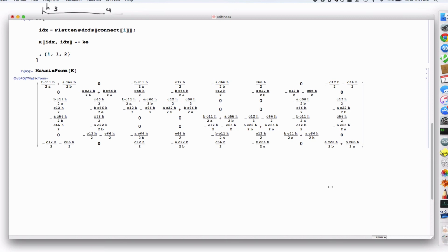I like Cubit because you can script it, right? You can drive it with their own internal commands, or you can drive it with Python. So you can script it and make everything parametric. You can put it in a loop and create 10,000 meshes at once, if you were doing some kind of sensitivity study or something like that. So that's why I like Cubit.